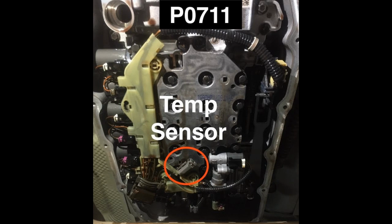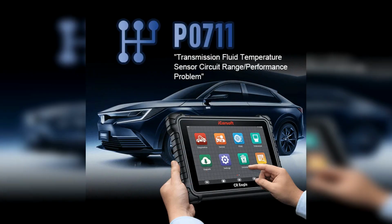The transmission fluid temperature sensor, TFT, is usually located in the transmission valve body, behind the oil sump. It transmits signals to the PCM to calculate parameters such as torque converter clutch (TCC) control, shift points, and line pressure. The TFT sensor receives a reference voltage from the PCM and adjusts its internal resistance according to the temperature